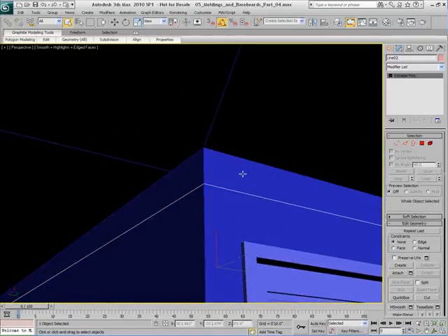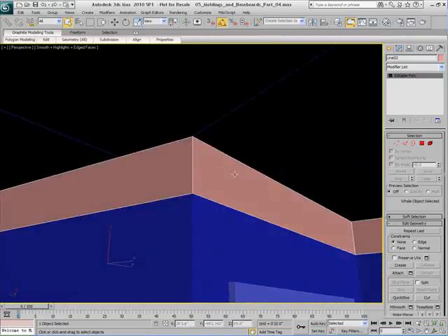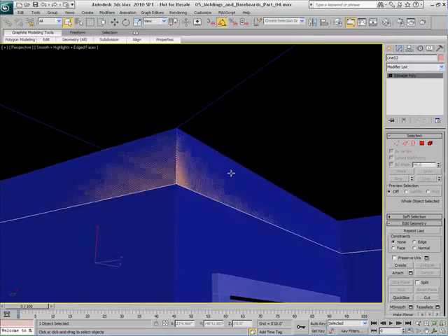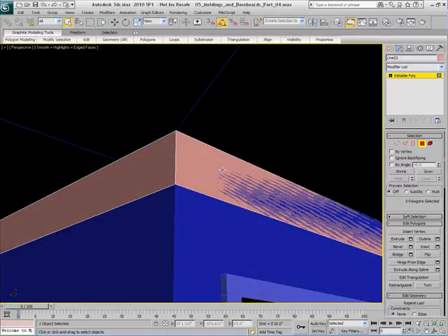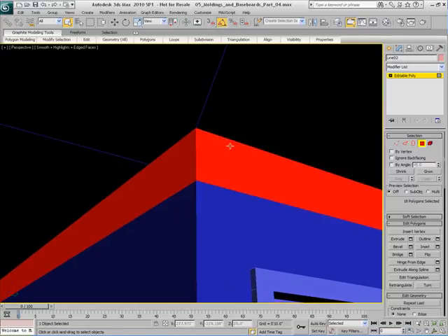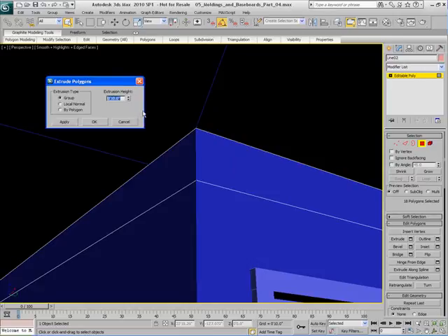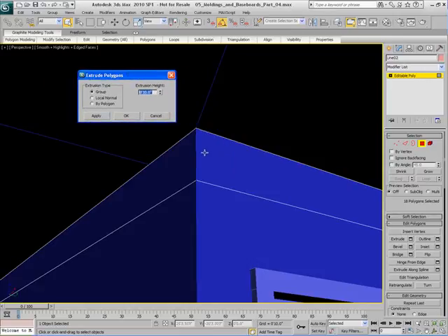Based on the reference images that I've seen and studied, I'm going to just create a molding out of my own imagination. So I'm going to do this on the fly. Here's how I'm going to do this. I'm going to select all the polygons here, and I'm going to extrude these. I'm going to go to the quad menu and open up the extrude options. I'm going to work with the tool options here quite a bit.